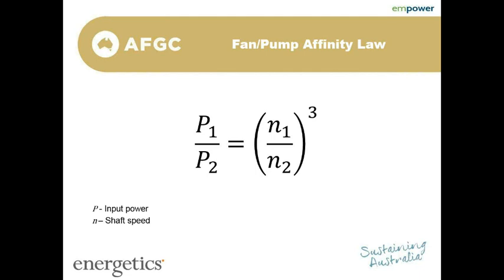So you can slow the motor down, reduce the torque, and reduce the pressure. So this equation really, we have two situations, case 1 and case 2. If you slow the shaft speed down by half, so you're reducing that required shaft speed by 50%, you then effectively have 2 to the power of 3, which is 8, reduction in the power required in that second situation.